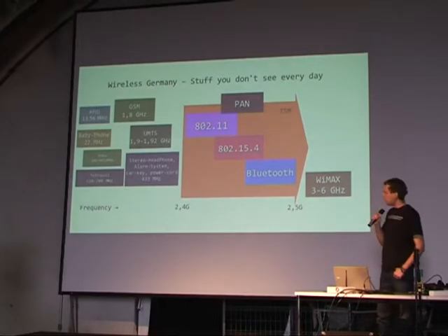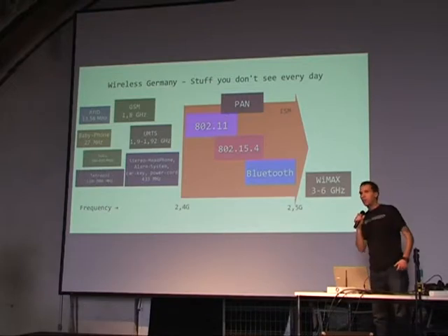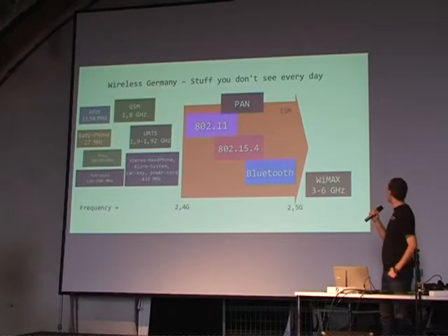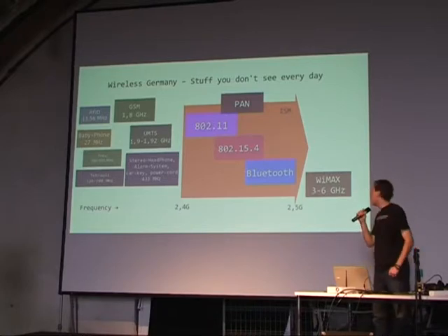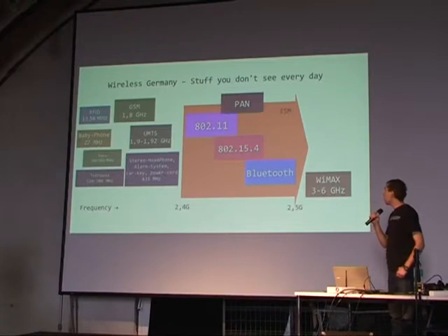And since I'm going to focus on wireless communication in the following, I've marked out the stuff in the ISM band, which you see marked with this arrow that is orange. Well, it's supposed to be orange. And you see that there is wireless LAN, there is Zigbee, and there is Bluetooth, and they all work in the same spectrum. So we can actually see that there might be some interference, since Bluetooth has adaptive frequency changes.